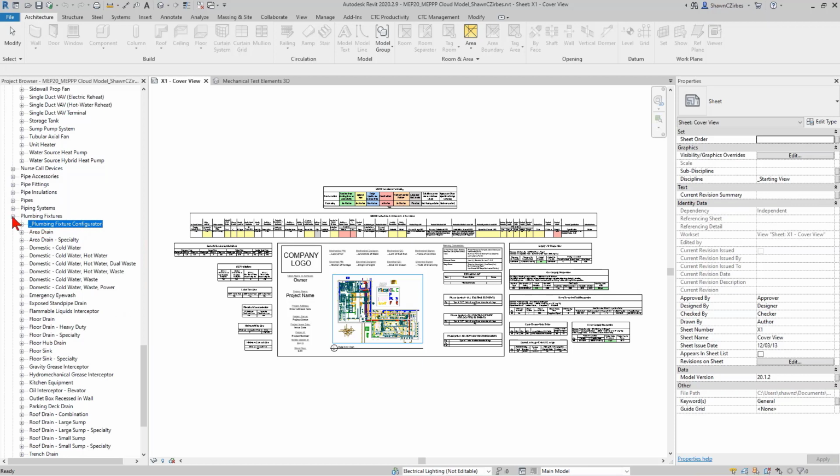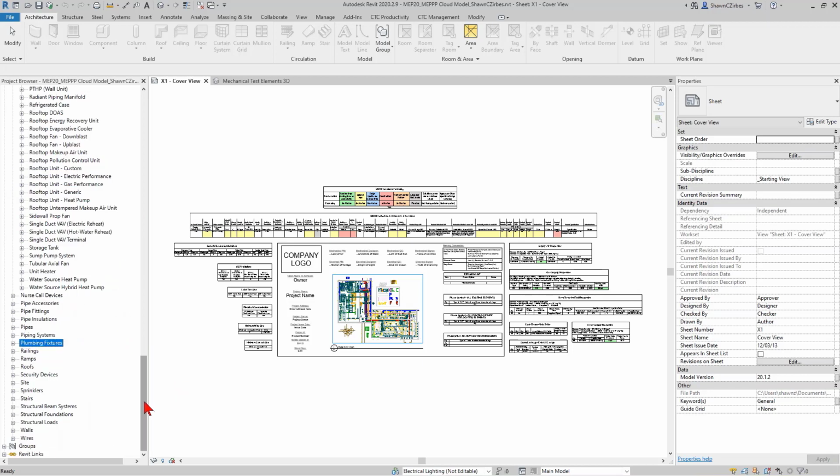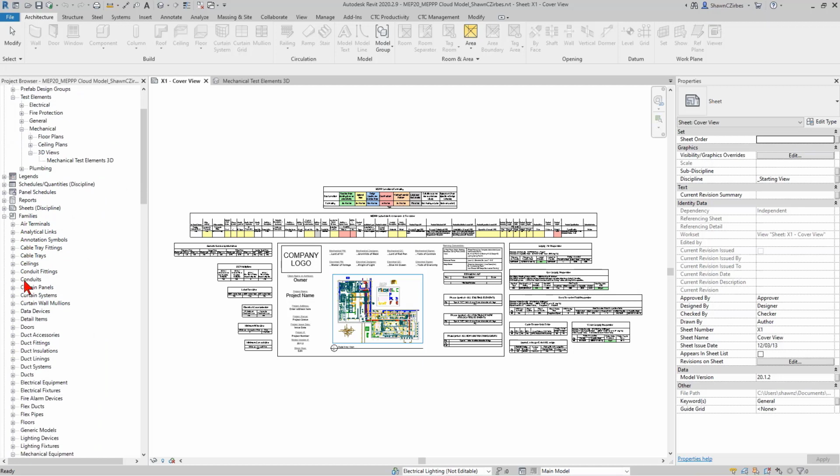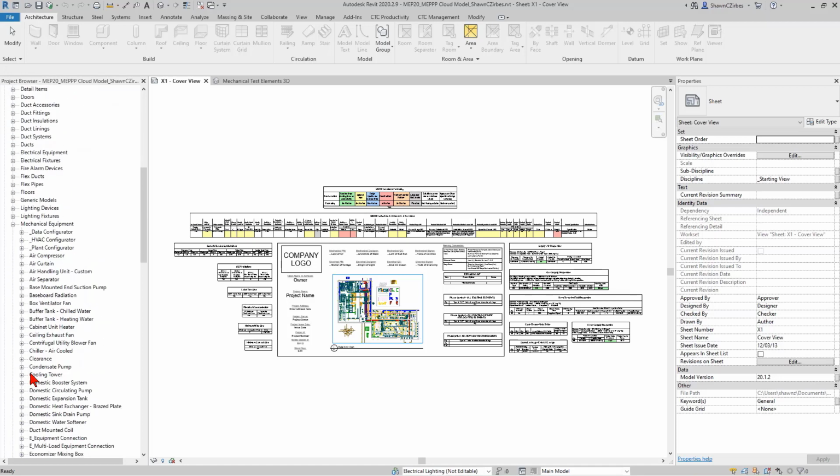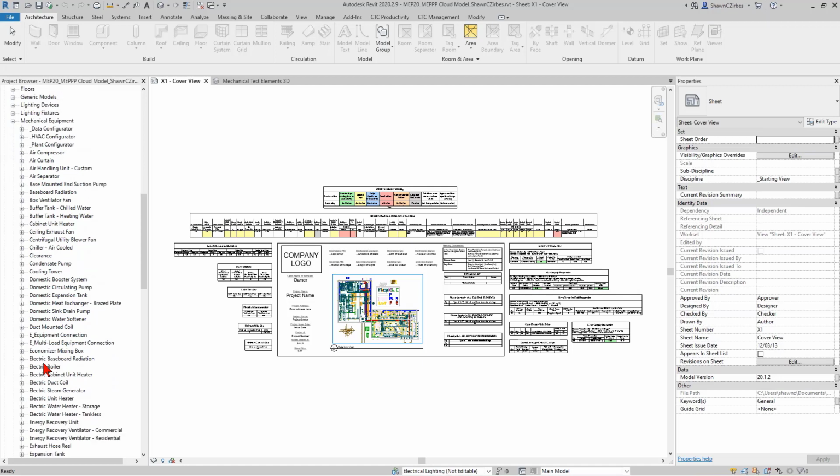If you needed some kind of a custom air terminal, which actually is one of the sessions we have planned in the future, we'll be up here in the air terminals area, and we'll be looking at these little underscore-prefixed ones, which are the default ceiling, exhaust, return, and supply diffusers or grills. And then you can use these to start something new. Now, below that, you'll see all of the custom ones that are pre-built. Another technique, instead of using just the baseline default, you can also start with an existing piece of equipment that's close to what you want. That's actually what I typically recommend. If I was going to build a brand new piece of equipment, I would look for something that's similar.